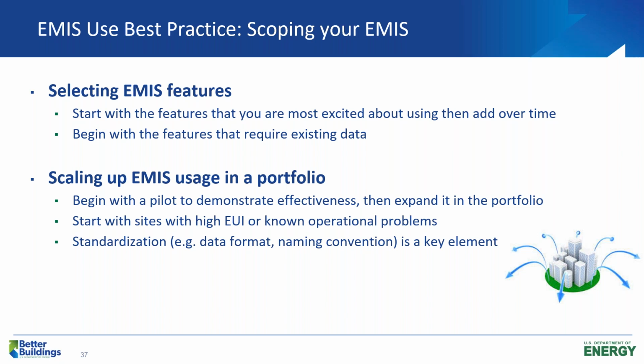Beginning with features that only require existing data. You know, nobody wants to add a whole new slate of sensors and then get all those up and running and then implement their EMIS. Most of these EMIS can really just use your existing BAS or your existing meters. You may have to add an interval meter here or there.